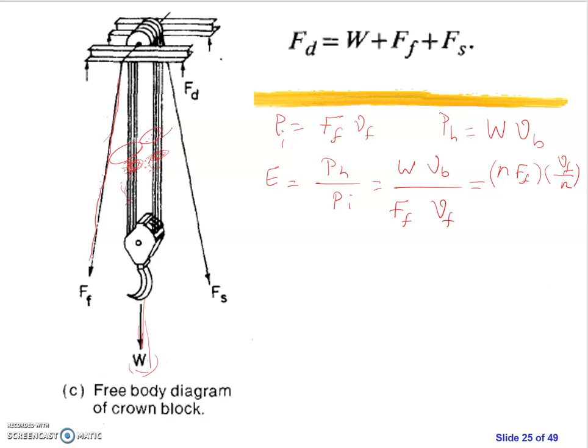So this fast line is moving much more than the whole system here. So if you pull this one for 2 meters and then you have 5 lines here, then these 5 lines will move by 2 divided by 5, right? Which means 0.4 meters. So if you pull this one by 4 meters, and you have 5 lines, assume, then 4 divided by 5 is 0.8 meters.